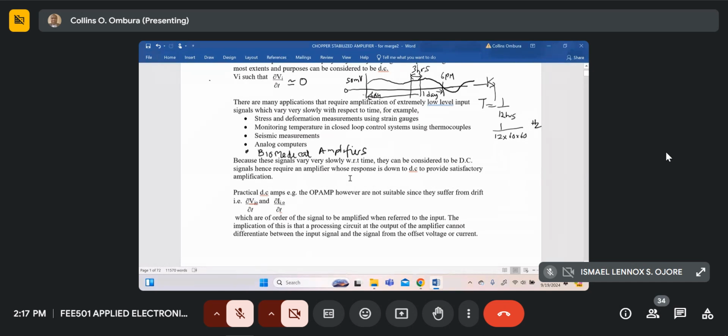However, the operational amplifier, even a modified one which is called an instrumentation amplifier, differs from a general operational amplifier in that the instrumentation amplifier is optimized to be very, very low noise. They make sure the transistors inside, especially those in the differential pair, generate very little noise.